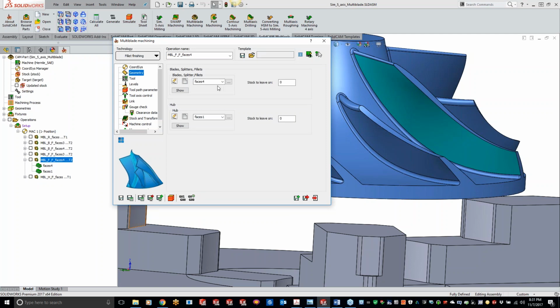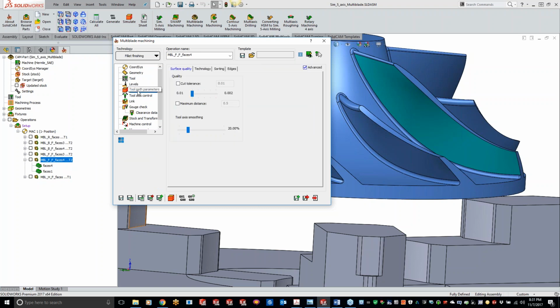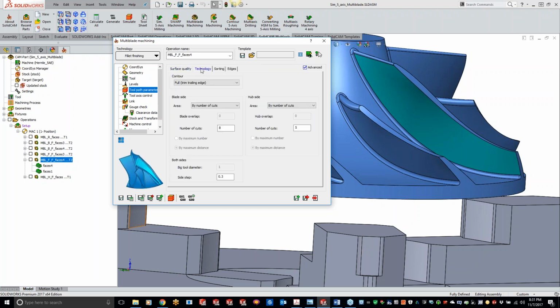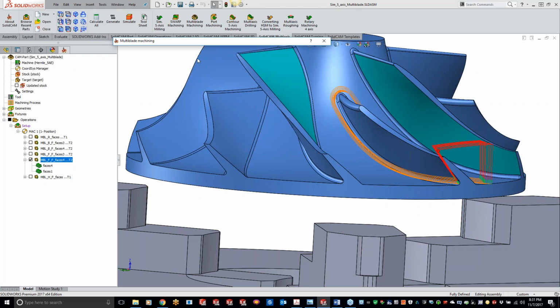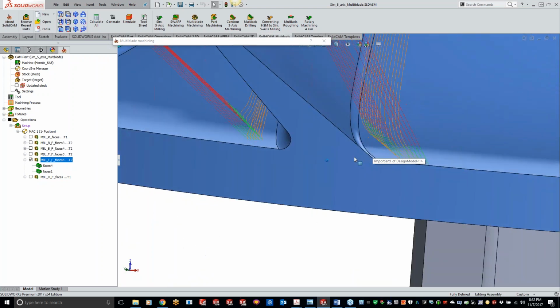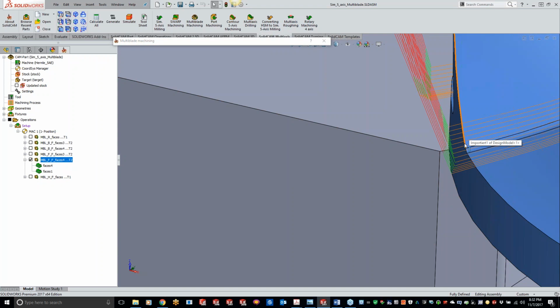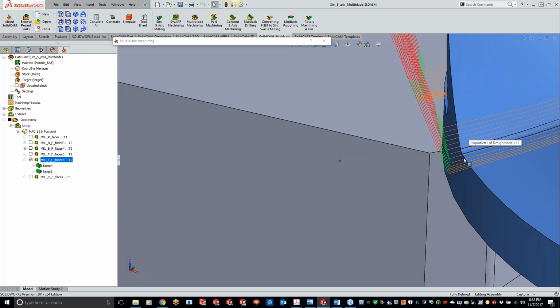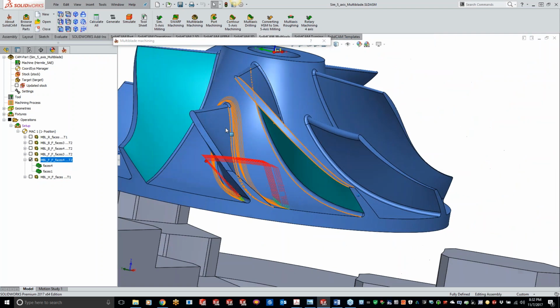Okay, so we got that faces 4 selected. Same tool, levels still the same right here. Toolpath parameters, all same. Pretty much just did, like I said, a save and copy and switched that faces over. Show up our toolpaths right here. Leaving our same steps, doing 8 steps up and 5 steps over. So you can see coming down 8 steps and then coming over is 5 steps to get a nice blend for that small radius going around that splitter blade.